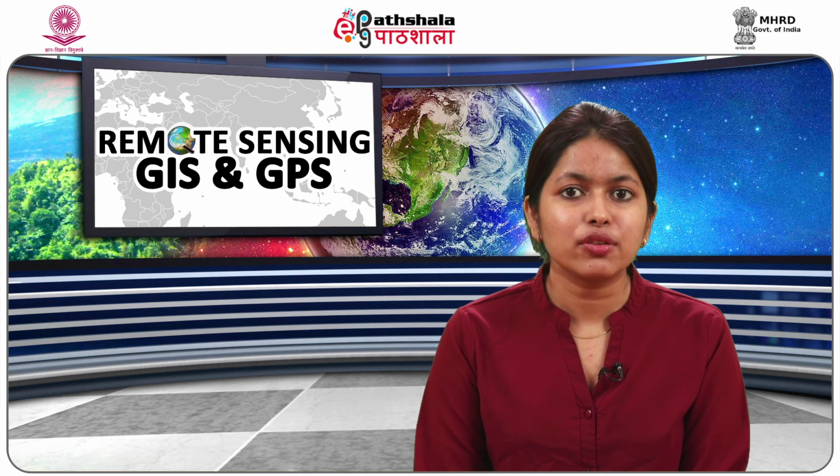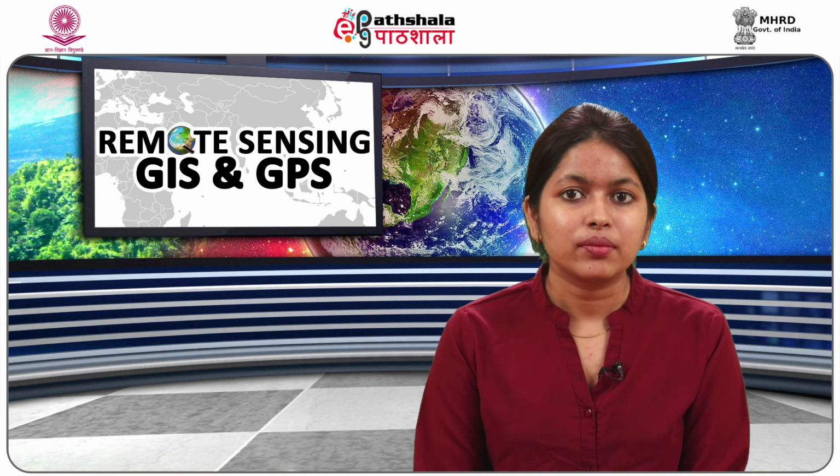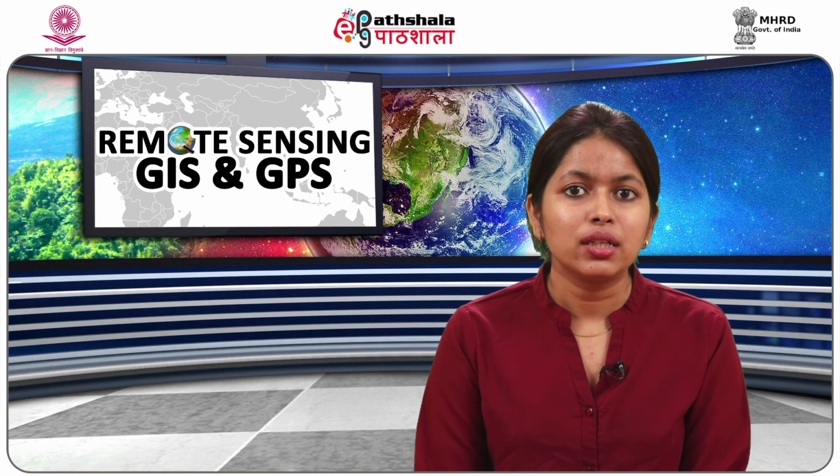Using light detection and ranging, data collected from the surveys covered 6 glaciers in Greenland and Antarctica. Particle image velocimetry was applied to temporally spaced point clouds to detect and measure surface motion. The type and distribution of the surface features, surface roughness and the spatial and temporal resolution of the data were all found to be important factors which limited the use of PIV to 4 of the original 6 glaciers.